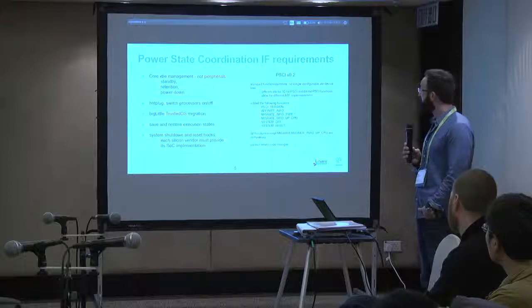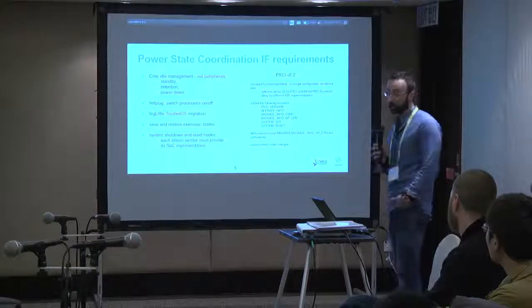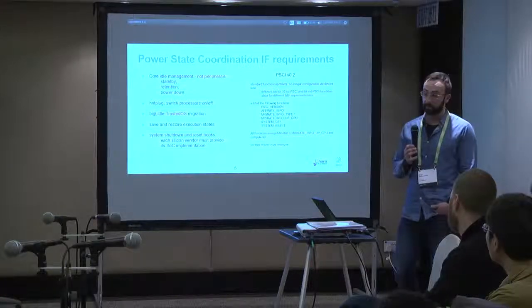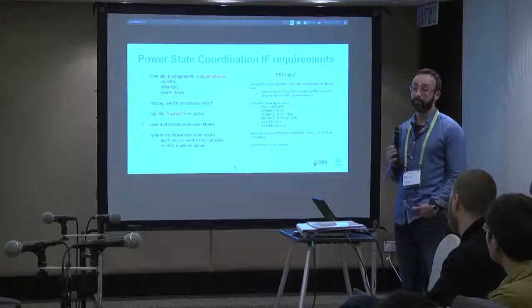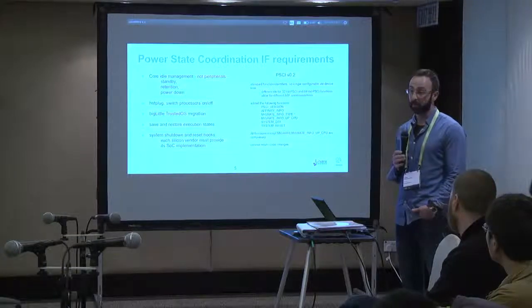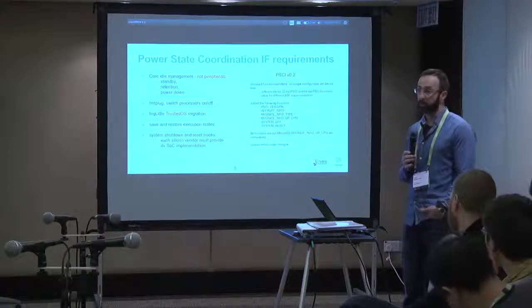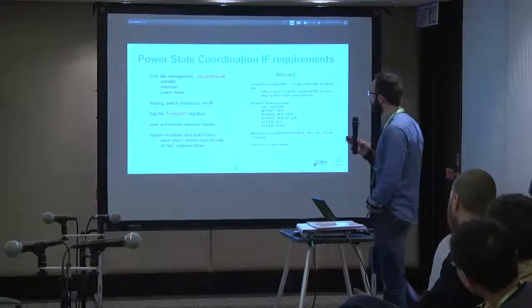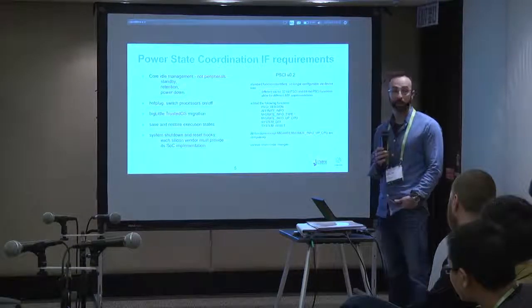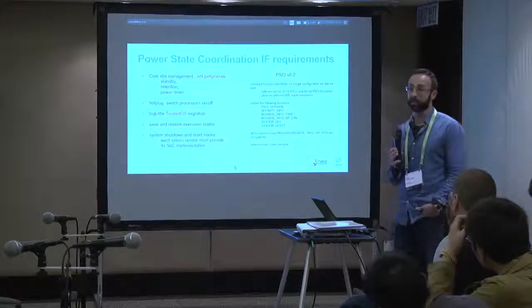Then it attempts to cover big-little migration, in the sense that for a trusted environment running on the platform, typically most trusted OSs, including OP-TEE, are not SMP capable. So if the supervisory software wants to suspend or power down one of the cores, it needs to contemplate the migration of the trusted environment to another core.